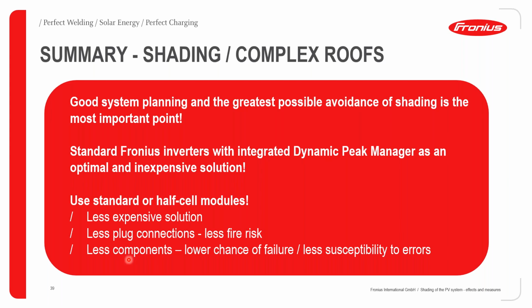If these shedding conditions cannot be avoided, then with an inexpensive solution such as the Dynamic Peak Manager from Fronius, you are guaranteed a solution that is going to give you as much power or as much energy yield from your system as possible. Going further, and as this becomes more and more common, you can use standard or half cells depending on the particular site conditions, and this can also extend to smart modules as discussed before. But this is going to be guided by what the analysis points you to after you've done a thorough analysis and simulation of operating conditions for your installed system.